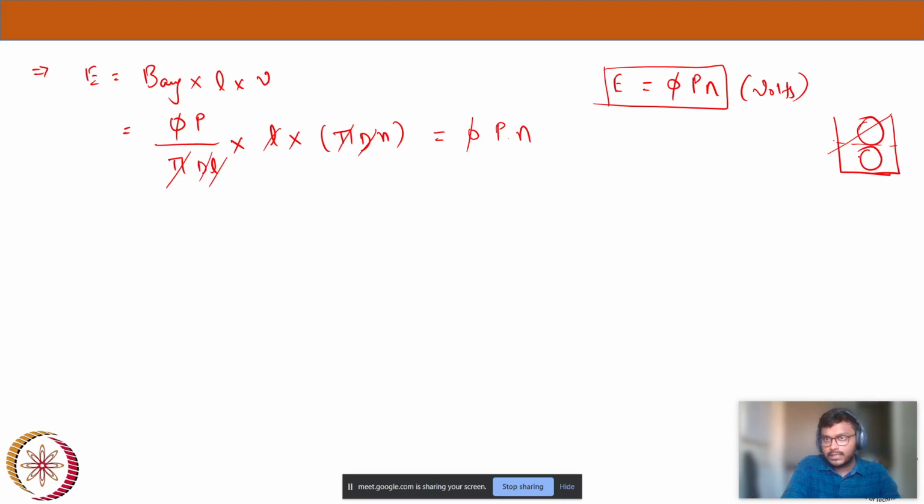So this is a single turn if you see like this, and I have turned it two times. This is a two turn coil, and this is a coil side, and this is another coil side. This entire turn will constitute the coil. Now, to get the number of conductors, you have to multiply the total number of coil sides into the number of turns. That will give you the total conductors.